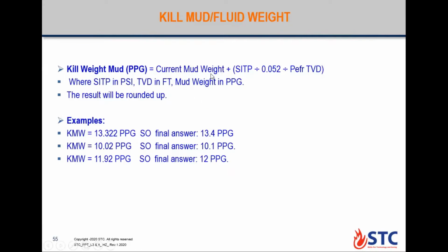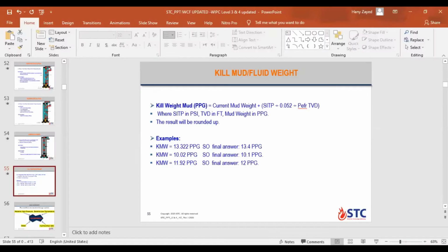This one? Yeah. After you shut in the well and after stabilization, you have an average fluid inside the drill string, like water or oil, and the formation pressure at that moment will be equal to the hydrostatic head. Let me write on the whiteboard.